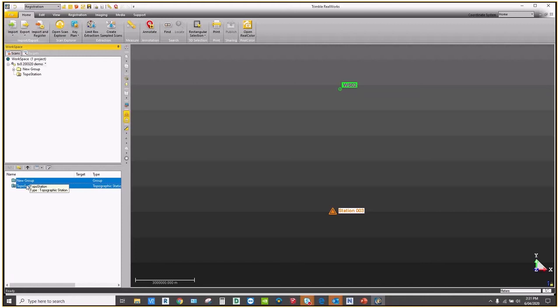set up over known marks. So one of the workflows that we like to promote to our customers is that you can do 100 scans. But as long as at least 2 of those scans are over known marks and you've got a method to register them, you're done. You don't have to get out the checkerboards and get out the jigger and start pinging survey control around the place. If there's existing control on a job, this workflow is just absolute gold. It makes it so easy.